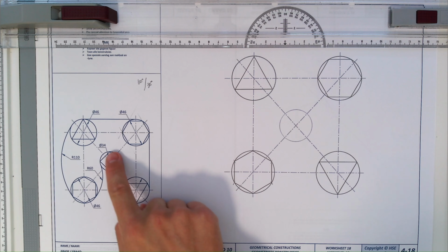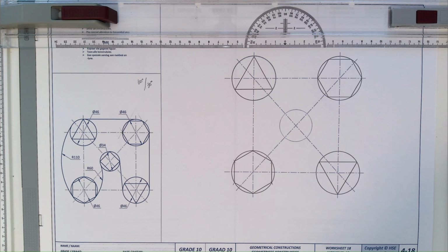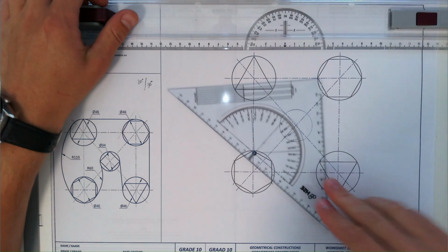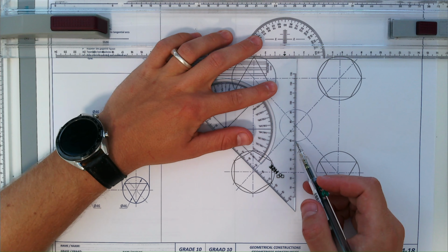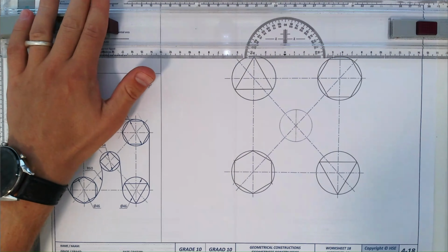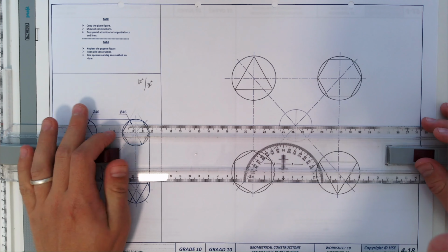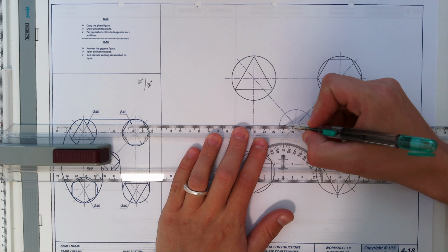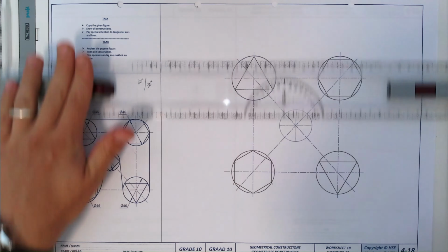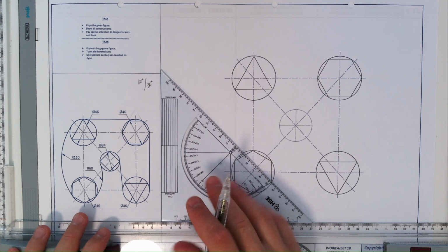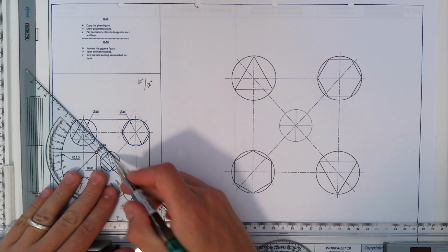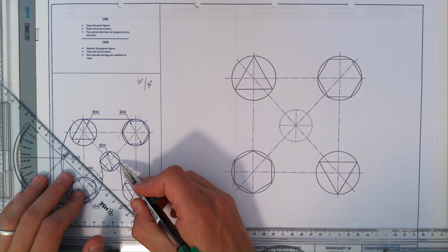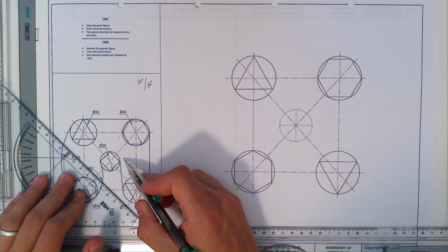Now we move our focus to the square. The square is rotated in a diamond-shaped form. So what I will do is, light in construction, draw a vertical line through the middle point till you get to the edges of the circle, and draw a horizontal line through the middle point until you get to the edges of the circle. Light in construction. A square rotated like a diamond shape, those sides will now be at 45 degrees if it is a regular square, meaning all the sides have the same length.